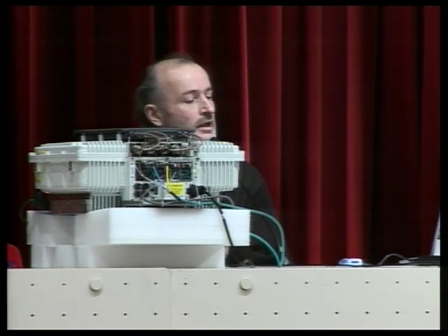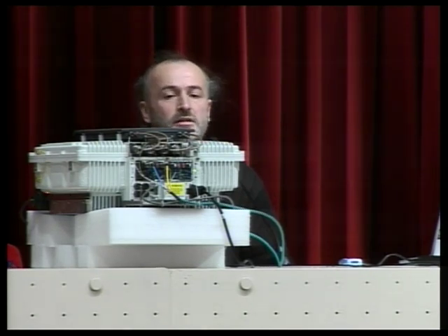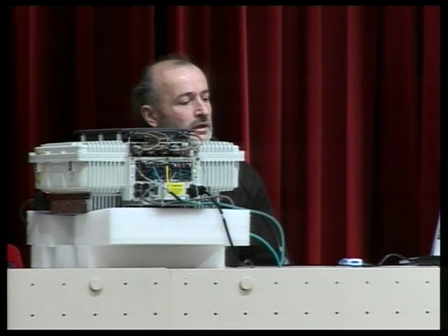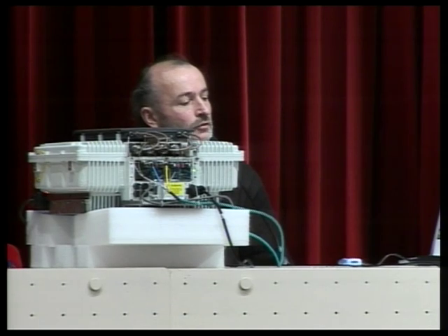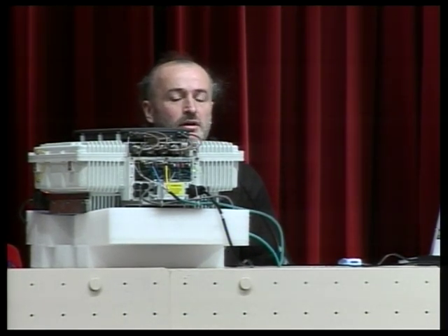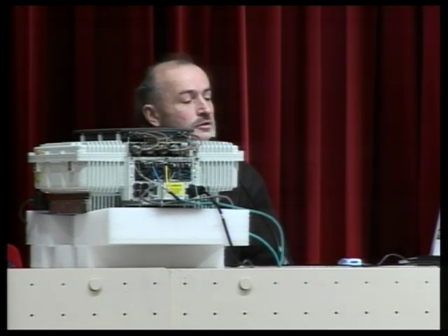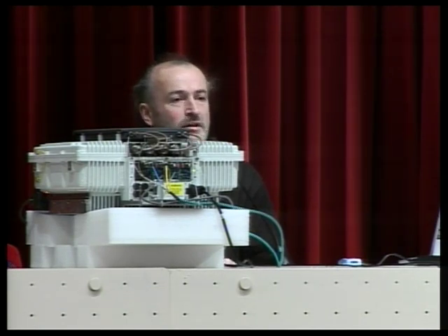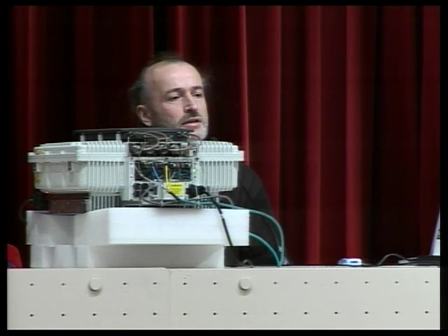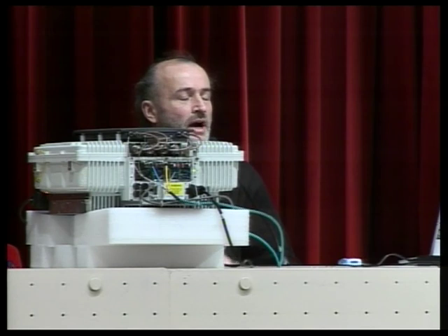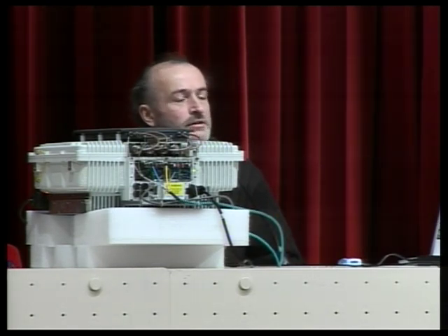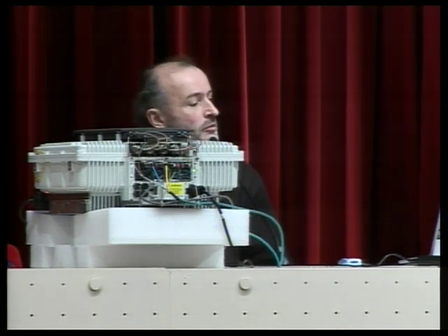In addition to this A-bis interface, which goes over the ISDN line, the base station also has a serial port. The serial port is connected to a program, which is also under NDA, called LMT, for Local Maintenance Terminal. The software is used by service people in the field. They can plug it into the base station, check certain settings and adjust some of them. But most of these settings can also be sent over the A-bis interface and are available in the specification. So this program is not that useful. If you don't have it, it does not matter that much. There are a few interesting commands, for example, the commands to set up the output power of the base station, and we will provide in the wiki the information on how to send a few bytes and get back a response from the base station. So if someone wants to use the few important commands, all of them will be provided, of course.